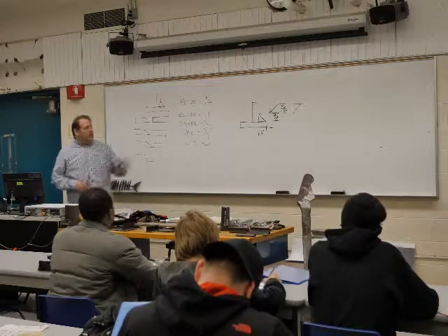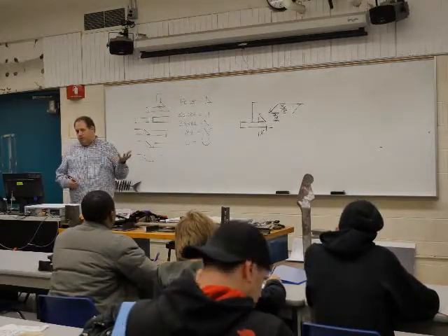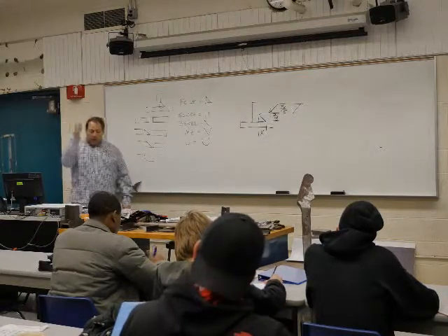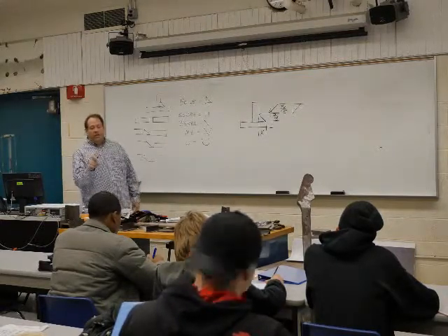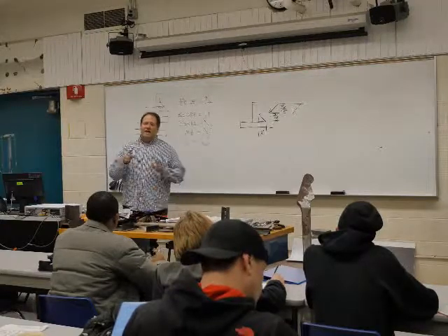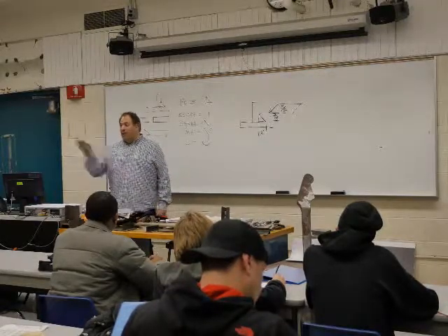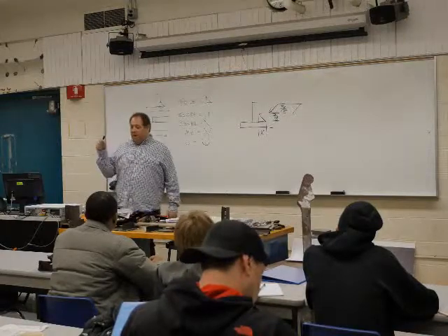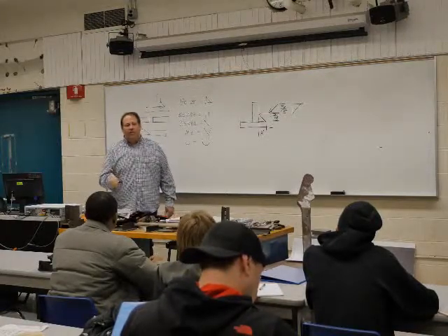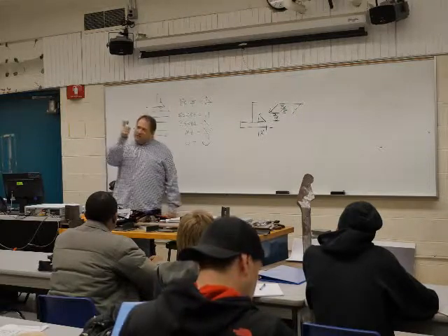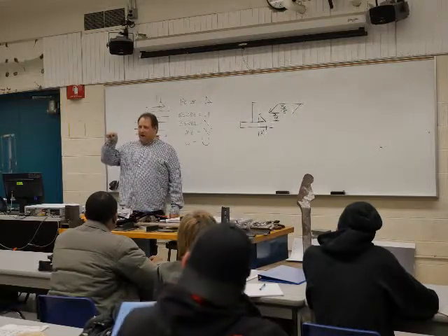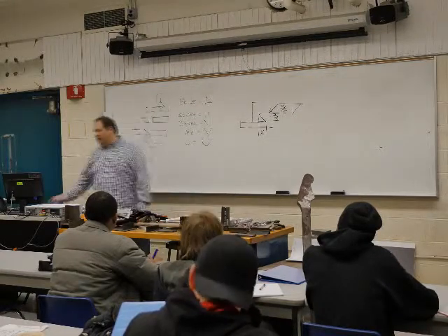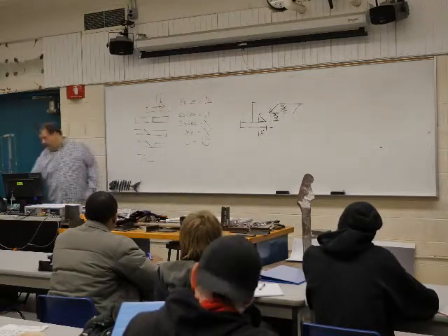Now, how do we measure that? That's kind of hard to measure necessarily when you weld this piece. It's pretty easy if we were to cut a section out of it. It's not really easy, but we polish it to where it's a mirror finish, and we dip it into a nitric acid bath, which then etches where the weld is in there. Now we can measure that weld. Realistically, that's not very practical.